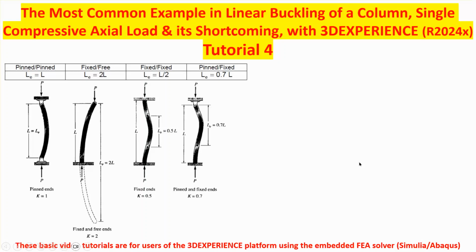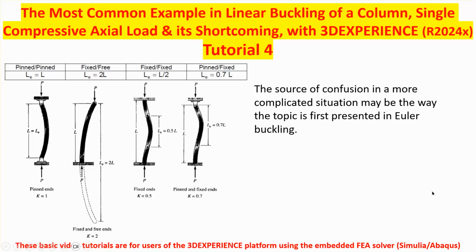Generally speaking, when we talk about buckling or we introduce it into our undergraduate curriculum, we concentrate on the Euler buckling problem, which can be any one of these, incidentally, depending on the geometry. And the source of the confusion in future, meaning the analysis that somebody may be doing with finite element packages, is maybe because this is introduced as a single load being present.